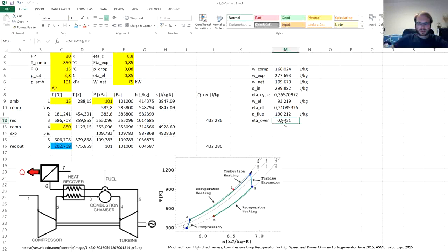This needs to be noted for calculations derived from the theoretical models, where we can assume the work output as the difference of the heat input and heat output. So just be careful if you have some other efficiencies on the work outlet further on. You cannot just use simple heat input and heat output, because there are some heat outputs hidden.